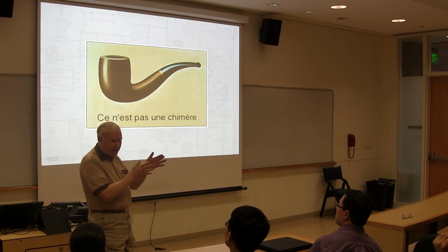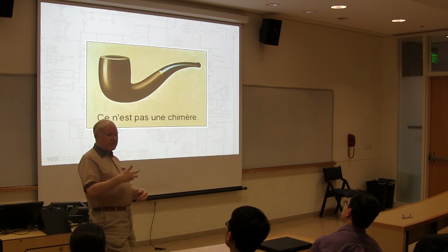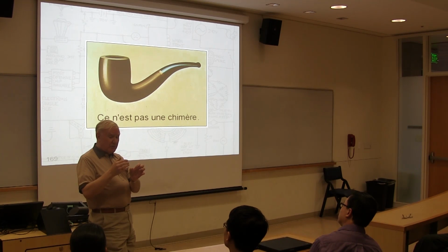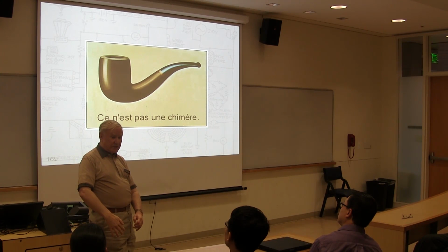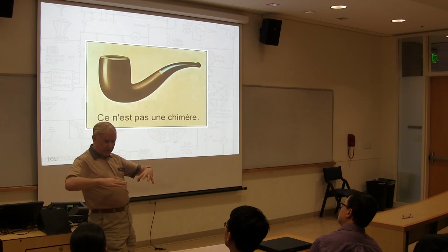This analog array normalizer, for example, is a very simple way of taking not just 16 channels. I didn't mention that there are 3 terminals that could be connected together, and you could parallel up as many of these devices as you want. So you can take 256 inputs from sensors and immediately come out with the normalized value. One of them is full scale and all the rest follow ratiometrically.